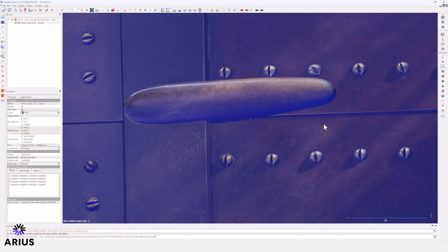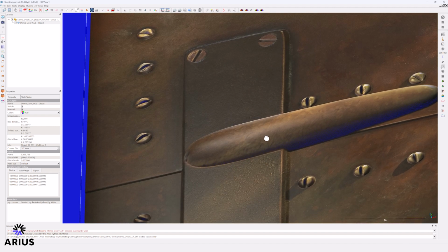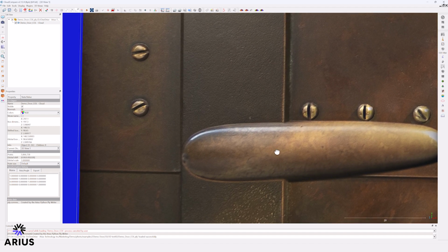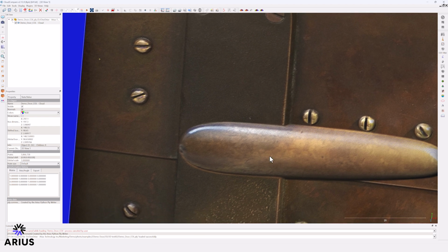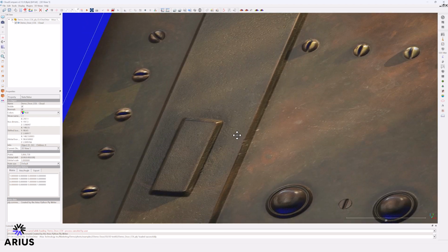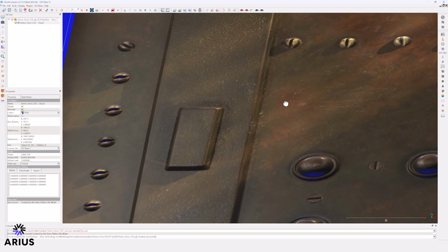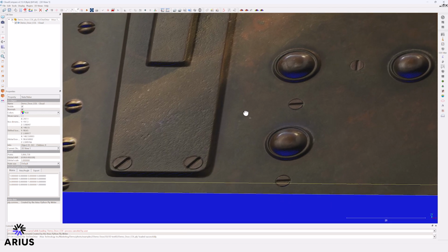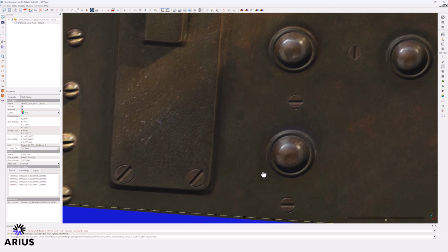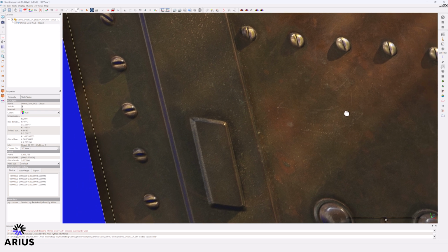Take into consideration the solid appearance of these points on the flat background surface versus on this rising slope. If you can see through to the empty world space, then it's possible the print will have a darkening of the color due to less material landing on the sloped surface. The larger the gaps, the more likely the color will print darker, but it doesn't need to be completely solid. The way to reduce the size of gaps around each point is to reduce the contrast in the elevation file, which reduces the slope.